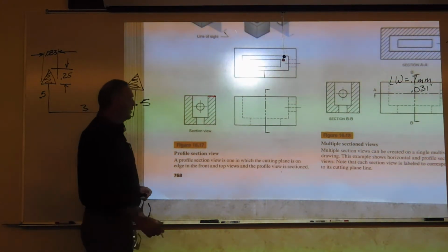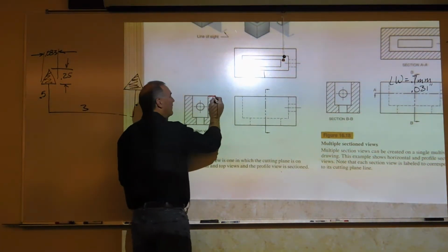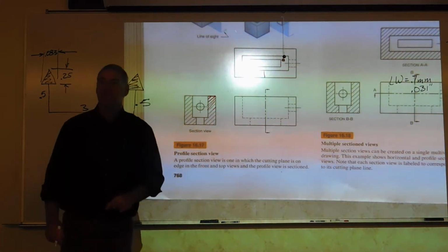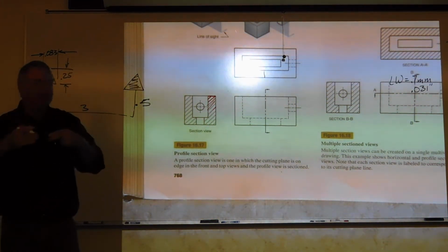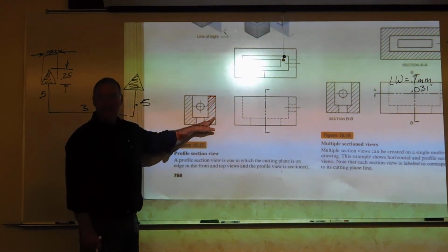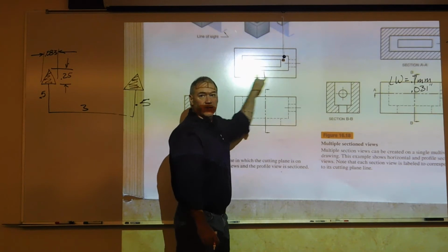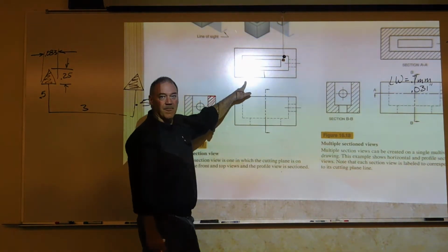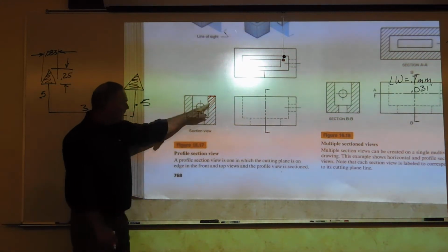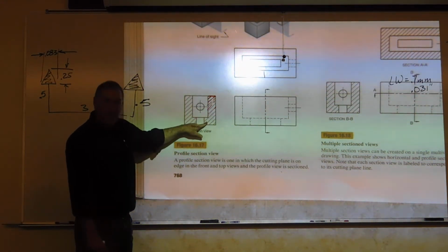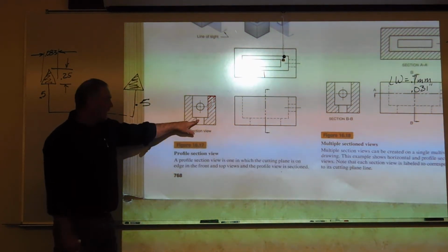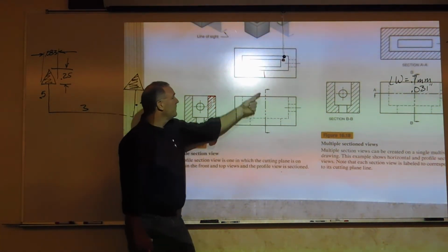As the cutting plane line goes through that, we would hatch that to indicate, hey, that thing has mass. I'm indicating a surface. Is this surface really here? No, it's not. It's continuous all the way through here, right? There's no edge. We're just doing it to show that this is where the cut is. All we're doing is saying this area has mass. It doesn't have section line here because it does not have mass. It's going through this hole right here, which is this one.